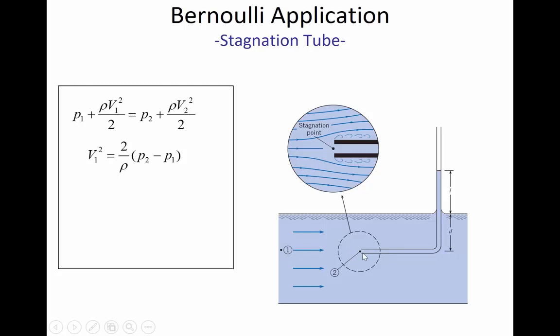Additional pressure in the amount of the velocity that was lost. That direct exchange of energy from velocity head to pressure head. So if we approximate the pressure at location 1 as the depth, here D is from the surface down to this horizontal plane multiplied by gamma. So in other words, we're just using the hydrostatic equation to find out what is the pressure at 1. Even though the water is flowing to the right, the hydrostatic equation would give us a pretty good guess of what's the pressure at 1.